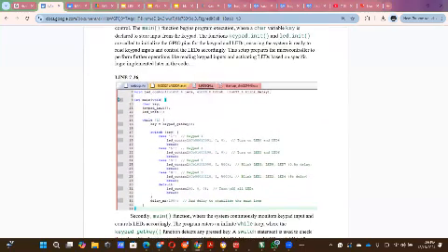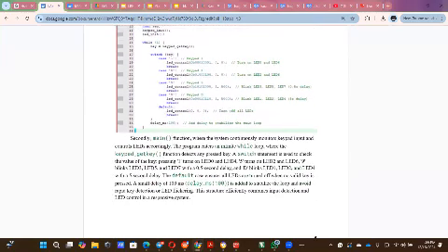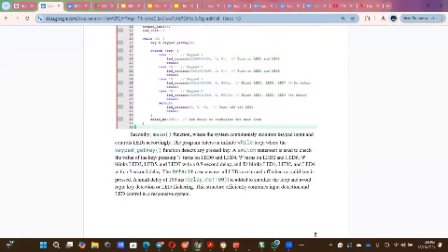For lines 7 to 36, this is the main function where the system will continuously monitor the keypad input and also control the LED accordingly. The program enters an infinite while loop, where the keypad get function will detect any pressed key, which is 1, 5, 9, and also D. We use a switch statement to check the value of the key pressed, where 1 will turn on LED 0 and LED 4.